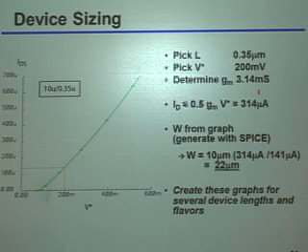Okay? So here's again where we're actually just going to use SPICE as a lookup table, right? Because as we said before, once we fix the V star and at least have a reasonable range for the VDS, then now we know exactly what the bias current for the device is for a given size of transistor. Okay? So just as an example, I could take a 10 micron wide transistor by 0.35 microns long. And I could take all my lookup tables and just sweep that V star. And what it would tell me is that if I wanted a V star of 200 millivolts, as an example, this 10 micron wide device would have 141 microamps of current flowing through it.